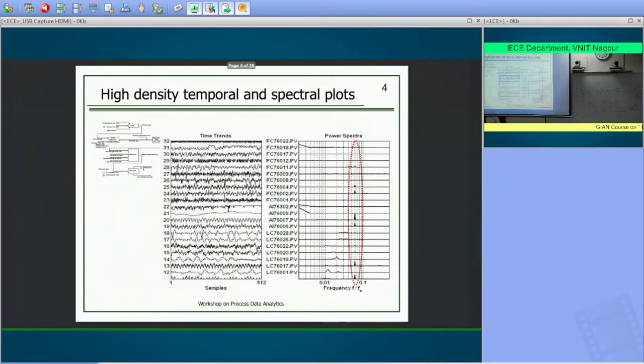These tags, the time series data, was collected from a refinery, and we noticed very quickly just by plotting that there are many variables that are oscillating at the same frequency. And it turns out that in this particular example, I believe there was a sticky valve that was causing oscillations in one variable, one control loop, and those oscillations simply propagated through the entire system.